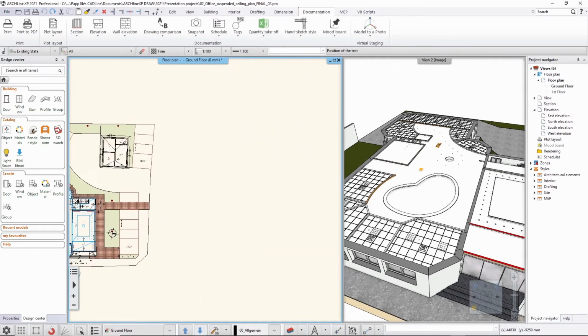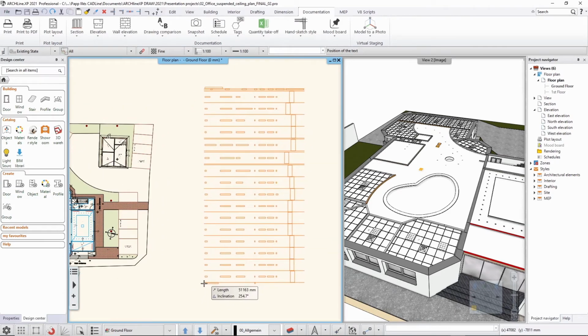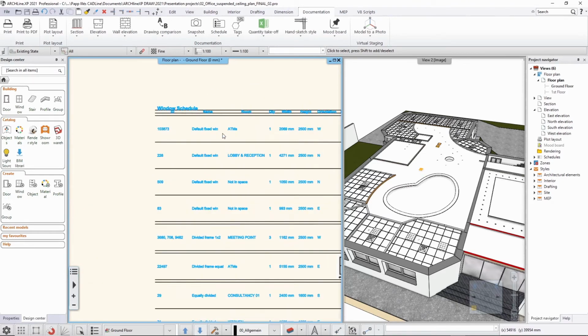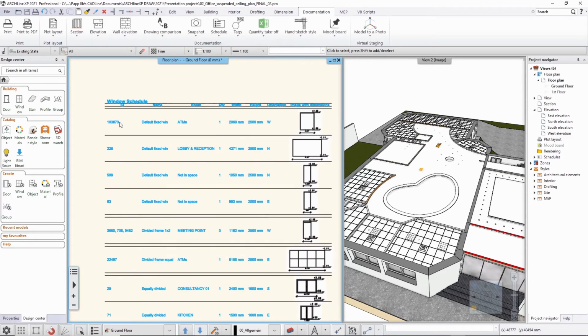it next to the drawing someplace here in the empty area. Now what I have here is the nice window schedule list with my custom text style, with the numbers of the IDs. Sometimes, because they are similar windows with exactly the same dimensions and the same window name, those are summarized, and that quantity tells me that there are 3 windows with the same exact geometry, width and height, and also the orientation is the same.